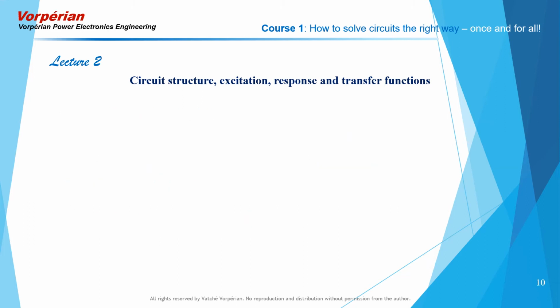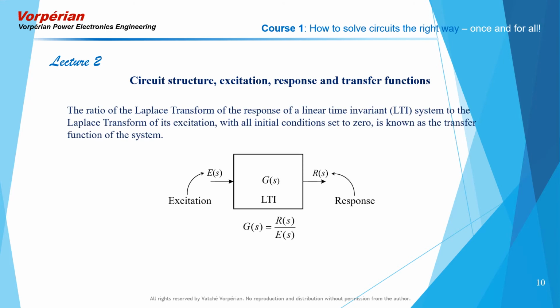I will now review the basics of transfer function as they pertain to the development of the extra element theorem. A transfer function, represented here with this block diagram for a linear time invariant system, is the ratio of the Laplace transform of the response of that linear time invariant system to the Laplace transform of its excitation, while all initial conditions are set to 0.